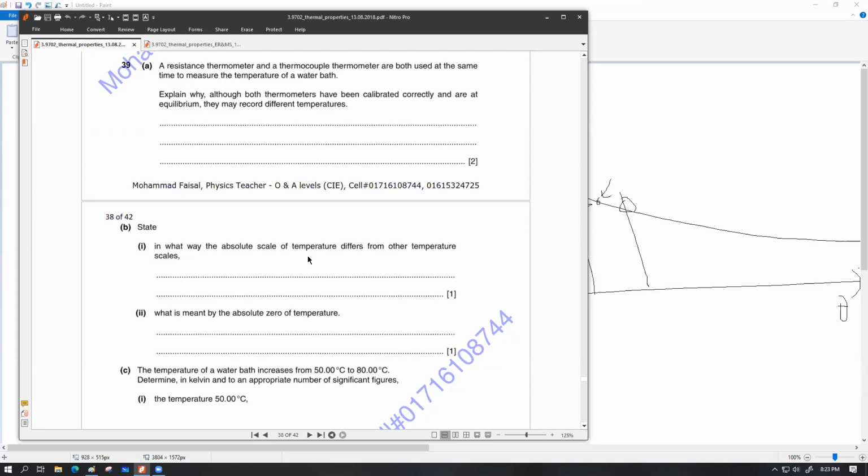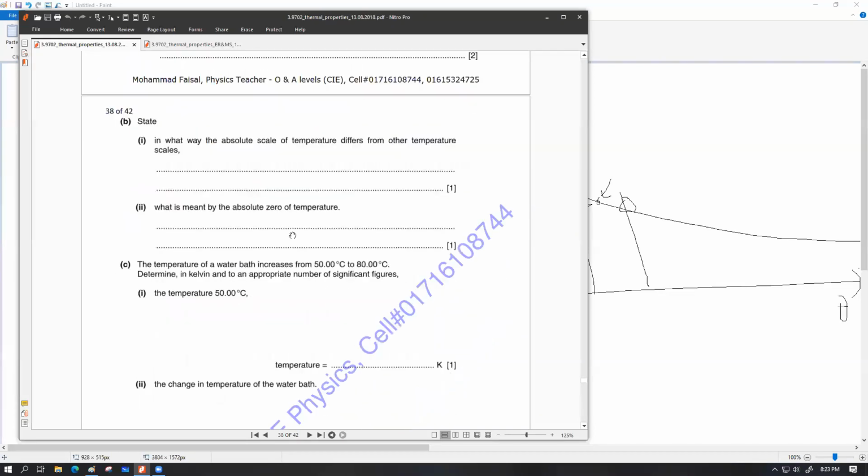So it's dependent upon our limitation of how precisely you want to measure with this device. The smaller you take your calibration gap, the more true your results are, and the more accurate your temperature is going to be for the in-between values. So the closer we come to the actual curve, which we can't really reach, but the more we do, the less difference there will be between the temperatures. Exactly. Okay, thank you, sir. Sure.